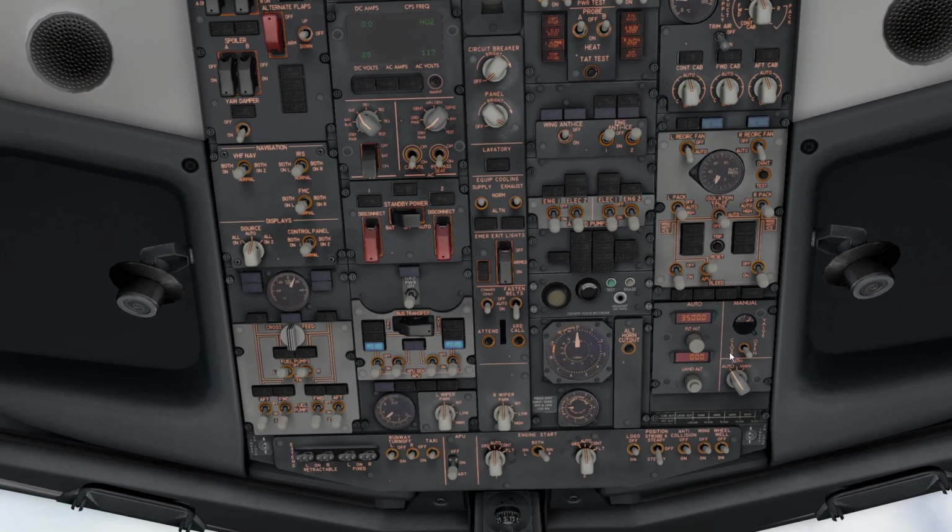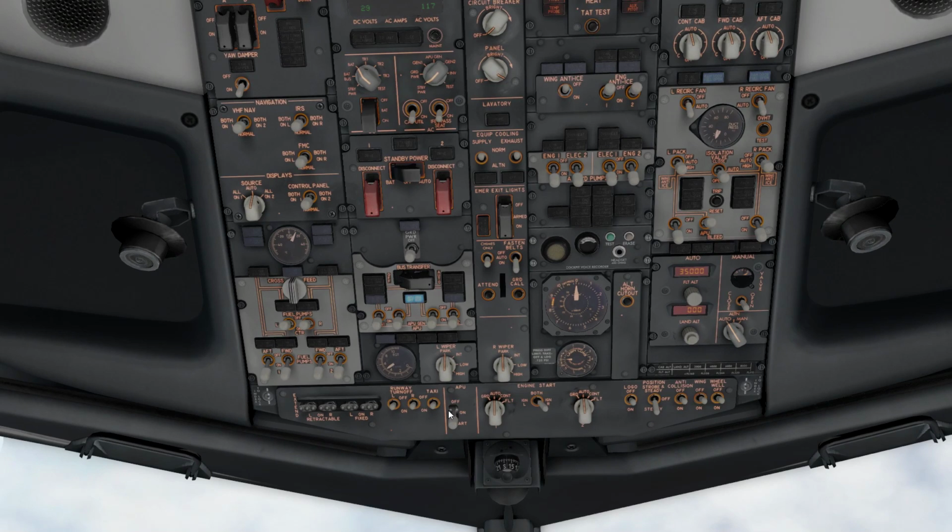Moving over to the second row, back where we had our electrical bus connections. A few moments ago we turned on the APU generators, and now we're going to go to our engine generators. Both engines are running, so we'll click the far left one under the blue light. Blue light extinguishes, and we click the right. Blue light extinguishes. You'll notice the APU gen off bus blue light has come on because the APU is running, but it has now been automatically kicked off the bus. Looking underneath it, down at the bottom of the skinny section, find your APU switch. You can now click it to off.